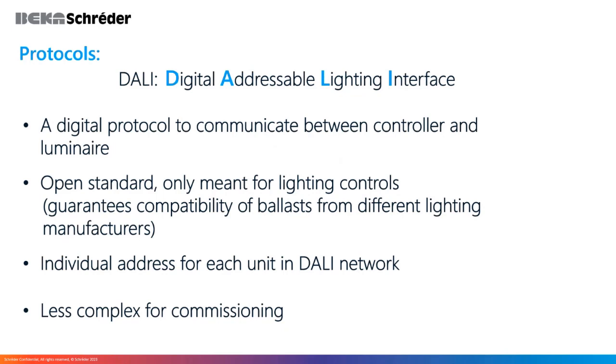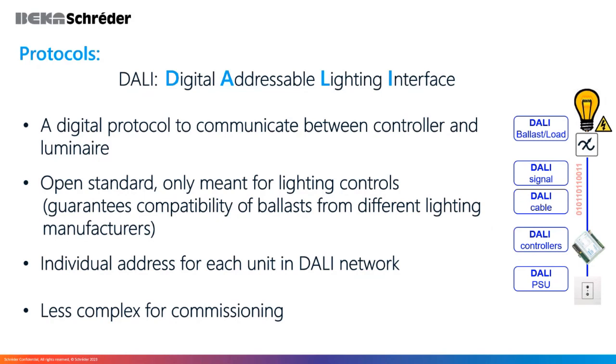It's an open standard across the industry, and compatible with different control gear, ballasts, and different lighting manufacturers. So it really gives you flexibility. And with the commissioning side, you have to individually address the specific driver for the DALI network, and it's slightly less commissioning if you had to look at the likes of DMX, etc. Just a bit of a graphic on the side there, just to sum that all up.